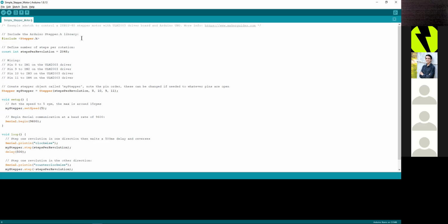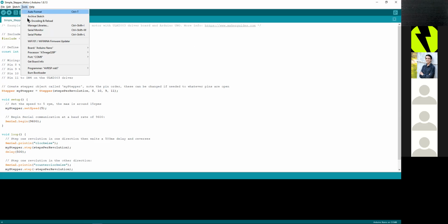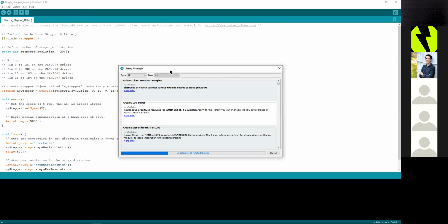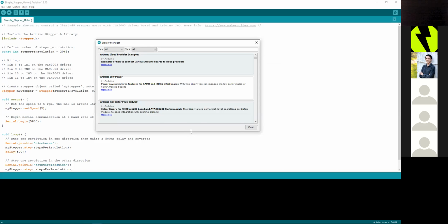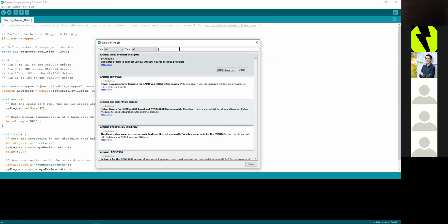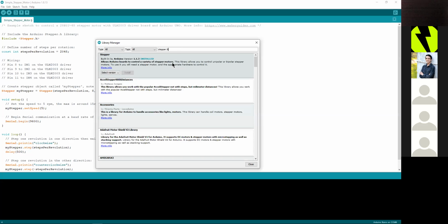On a side note, for this specific program, you're required to download the stepper library. A lot of programs require peripherals and need libraries to make it easier for you. To do that, you go through Tools and choose Manage Libraries. That pops up, and then you have an entire list of different libraries. For example, the one for the stepper motor is Stepper.h. As you can see, I installed it already.